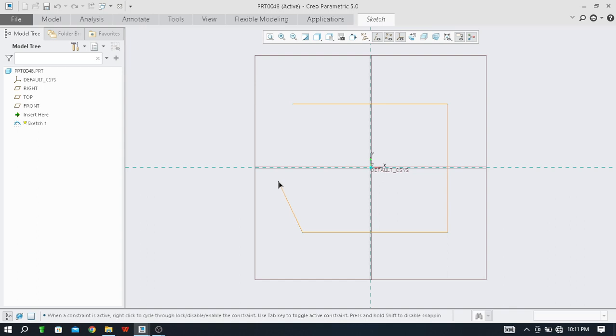I want it to close, and there are two ways. I already told you the first way, which is the middle button of the mouse; we just have to click it. The second one is to click on the Escape button on your keyboard 2 times. After the first escape, the line will be unable to draw, and if you click the second escape, then automatically all the dimensions will be created by the software.